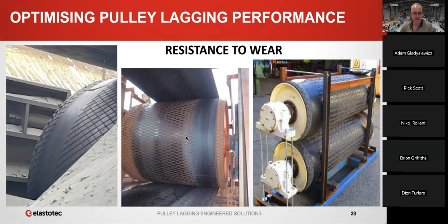Now, I don't think that was just due to abrasion resistance. If the lagging that had been put on here had been the extreme rubber, we would not have got 3 years. It was the combination of the much better abrasion resistance and the low surface energy, so that the shear stresses that were occurring from the contact with the belt, it was able to slide on the polyurethane.